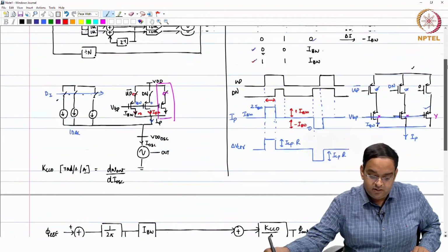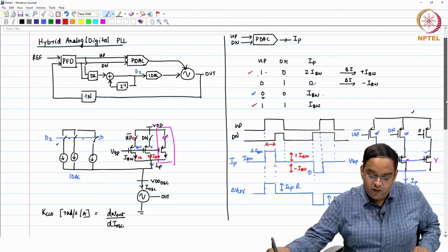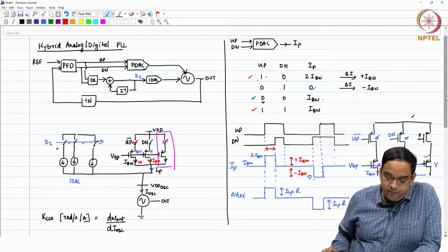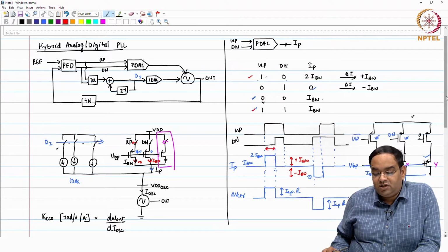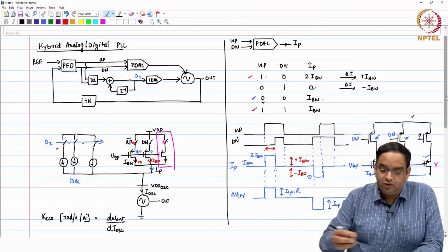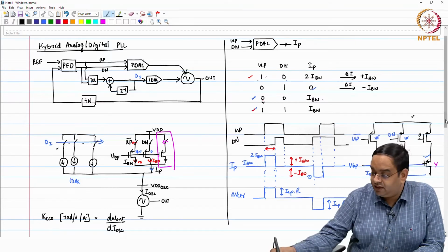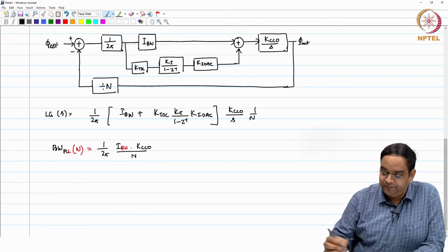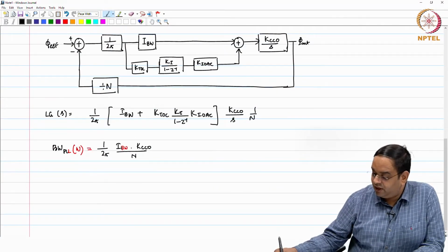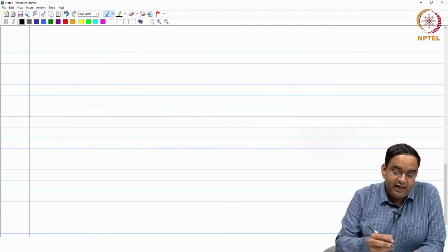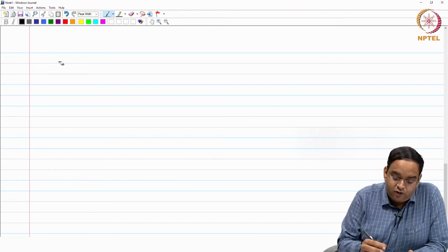Okay. So, now given this hybrid PLL, analog and digital, and the proportional digital path control, let us look at how we are going to control through this IDAC, because this IDAC normally has a problem of resolution versus range trade-off. So, what is typically done? Let us just consider the IDAC path and the current controlled oscillator.